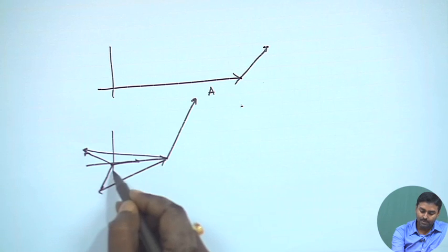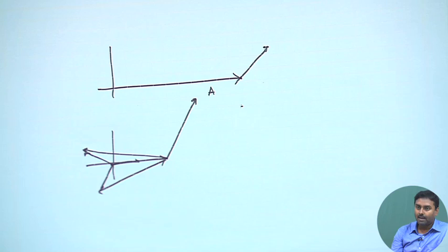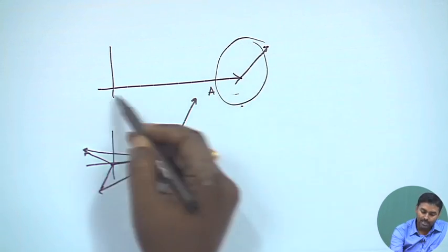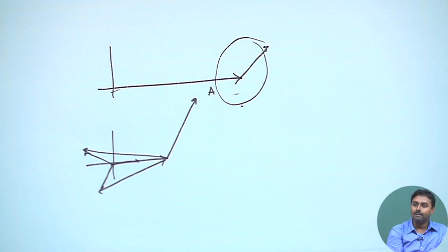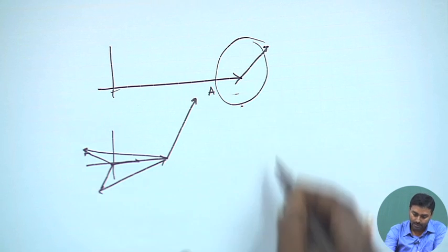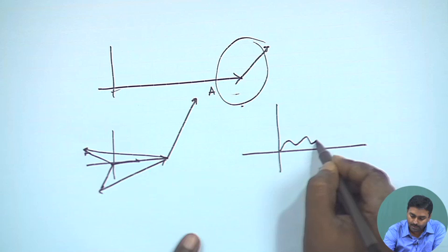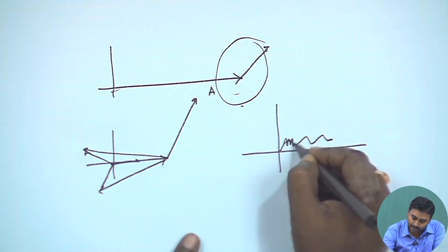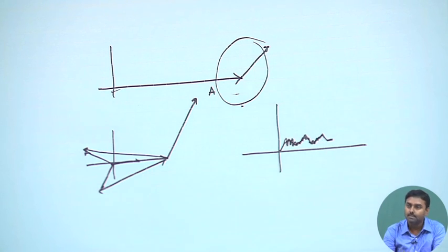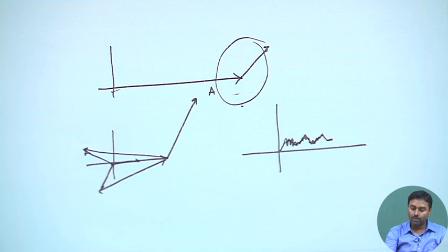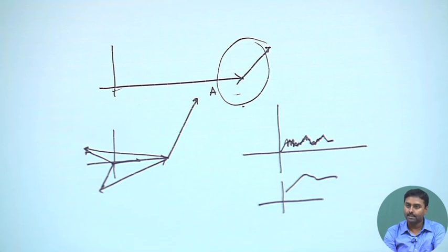So, there might be a random variation of phase which was not happening over here. Here if it wanders, I know that it will still remain around theta. So, it is not getting a huge variation due to noise. If you plot that theta, I wish to have a theta variation like this, and on top of that there will be small noise induced theta variation. I will differentiate it, they will smoothen out even more and I will get my actual message signal variation.